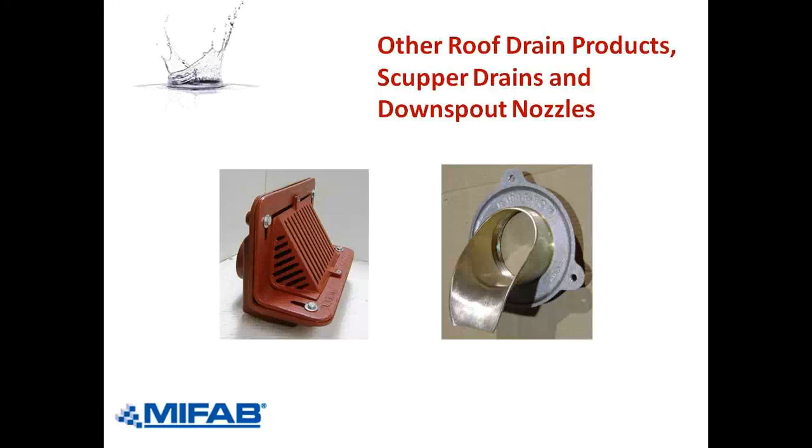The secondary is insurance. In the event that the primary roof drain gets blocked, the water will then have to flow down the secondary. But we don't want the water to go into the secondary right off the bat. That's why we have the dams, either the external dam, the R1200-R, or the internal standpipe dam, the R1200-W. When water does go down the secondary roof drain, it doesn't go into the sewer. It typically goes through the downspout, which is what we have here on the right.